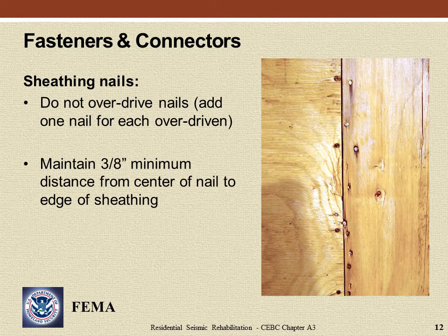Nails are considered to be overdriven when the face of the sheathing is fractured by the sheathing nails. Many of the nails in the above photo are overdriven. Properly adjusted nail guns will not overdrive nails. Where nails are overdriven, the capacity is significantly affected and additional nails must be provided.